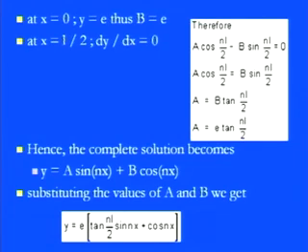So keeping those values at x equals 0 and x equals L by 2, we have a cos nL/2 minus b sin nL/2 equals 0, or we can simply calculate a, which equals b times tan nL/2. You see here we already calculated the value of b, which is the eccentricity e. So we have the coefficient a equal to e times tan nL/2.